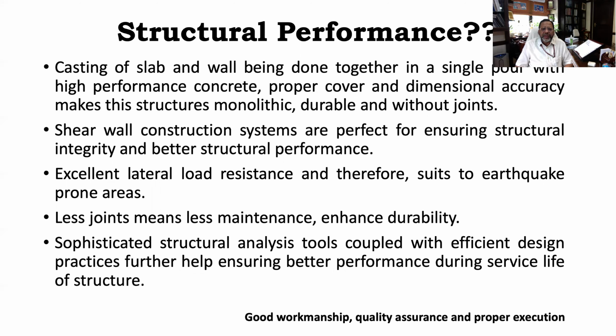Number one. Secondly, with casting of wall and slab done in a single pour using high performance concrete, proper cover and dimensional accuracy, the structure is monolithic, without joints, and durable. And being without joints, there are no problems of leakages, and there is less maintenance. Less joints means less maintenance, less leakages, and a durable structure. So it enhances durability as well.